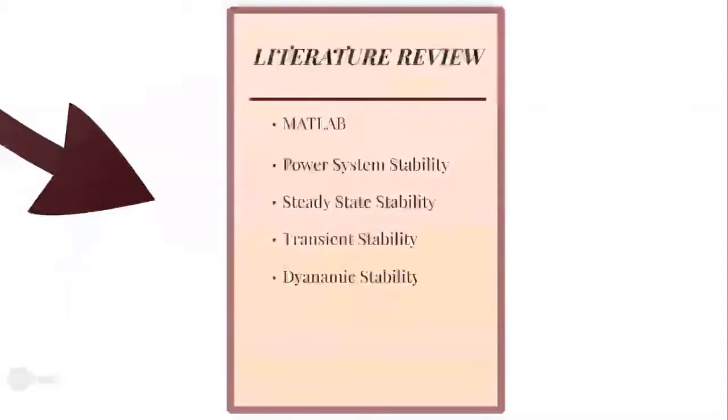For transient stability, it is the ability of the system to reach a stable condition following a large disturbance in the network condition. This covers all cases related to large changes in the system, like sudden application or removal of load, switching operation, line fault, or loss of excitation. Dynamic stability also denotes the artificial stability given to an inherently unstable system by automatic control.